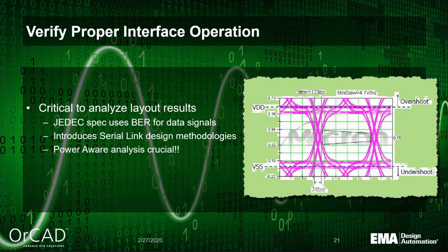The channel technology is a little bit different than full-on time domain analysis that you normally do with a parallel bus interface. The channel approach allows you to essentially use a lot of data bits down the channel in a reasonable amount of simulation time. So that's why this is particularly favored to analyze the DDR interface.